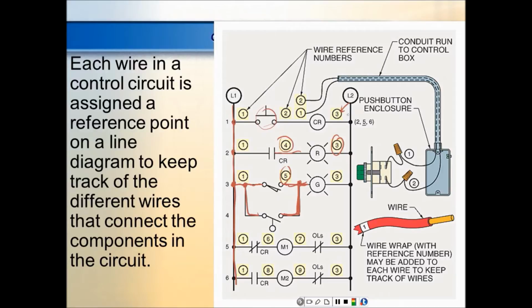So over here, all these are connected together. So if I took an ohm meter and I put it way up here on L2, I remove power, and then I put it all the way around there, it's going to show me continuity. It's going to show me 0 ohms, or way down in the tens. A lot of times a meter will measure the meter leads. But these two are connected together.